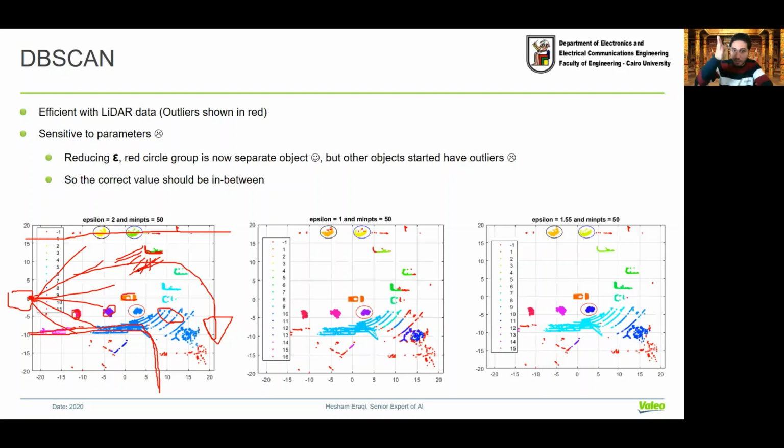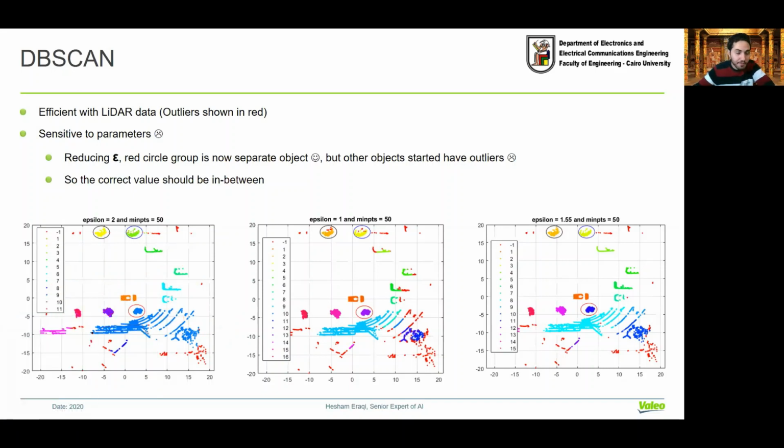But if the vehicle is just in front of you, something like this, you get U-shaped scan points. Okay, that's clear, all of this. So this is a top view cloud of points that are received from the laser scanner at some moment. If you give this cloud of points, you don't have ground truth for all of these points. Beforehand, you will not be able to tell whether these points belong to the same object or not, the same cluster or not.